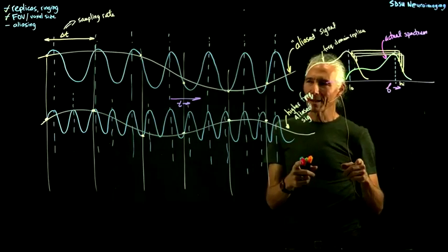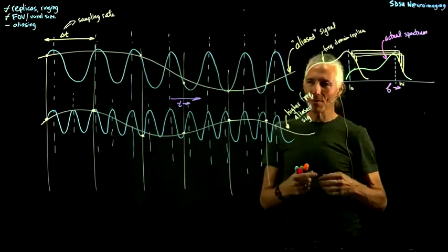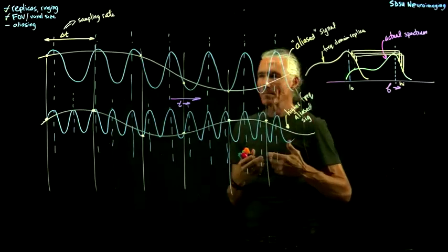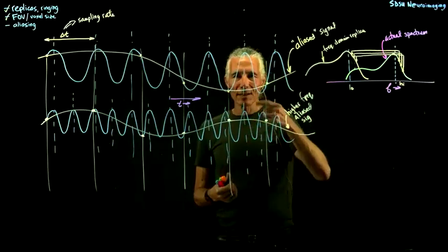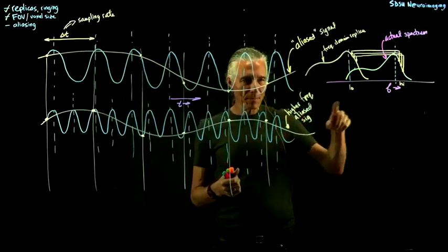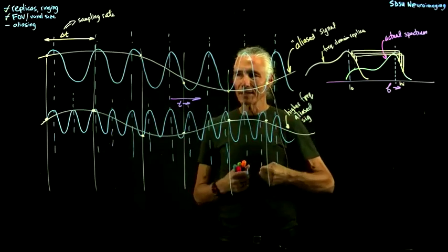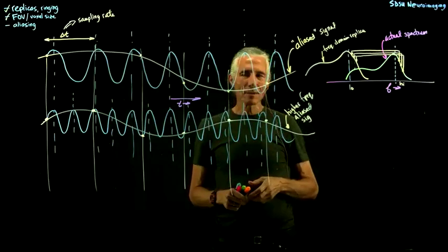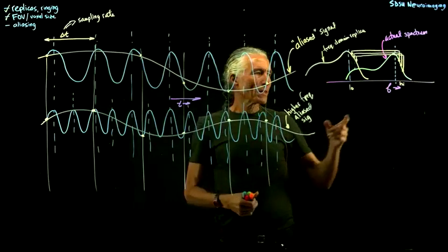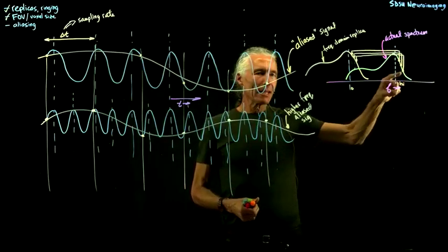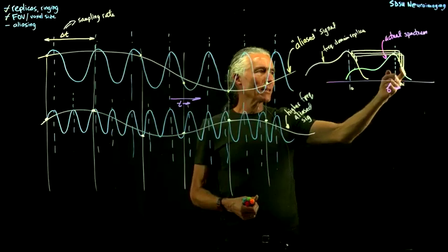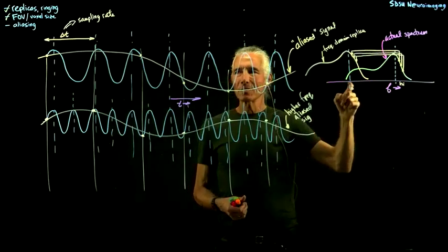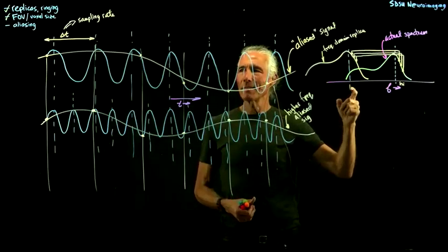And so what is that going to do? Every time your heart beats, it causes the oxygenation to increase, and so you end up with a bigger signal every time your heart beats. It's a pretty big variation in the signal because it's pumping oxygenated blood and you're measuring the effect of oxygenated blood. And so what's going to happen is that signal, which is off the edge, you're not recording fast enough, is going to appear as a frequency signal in your time series at a very low frequency.